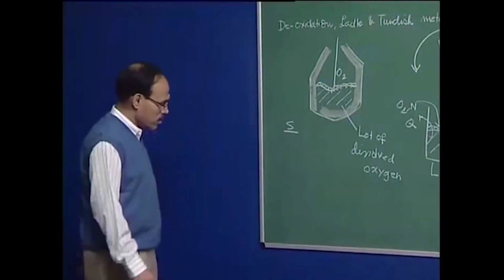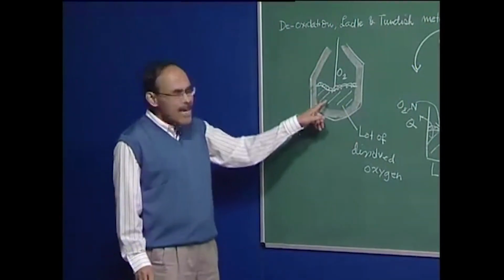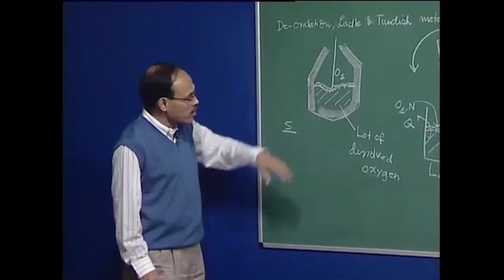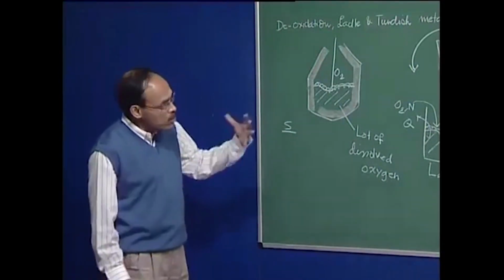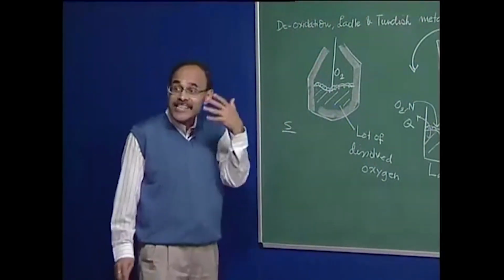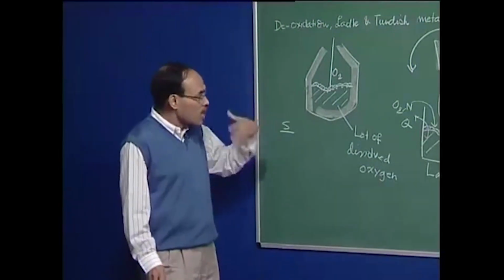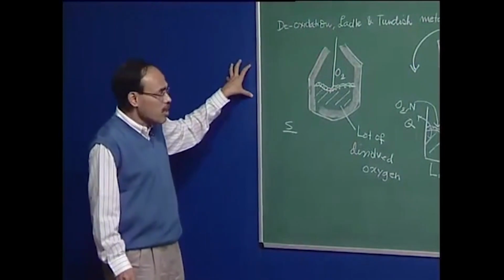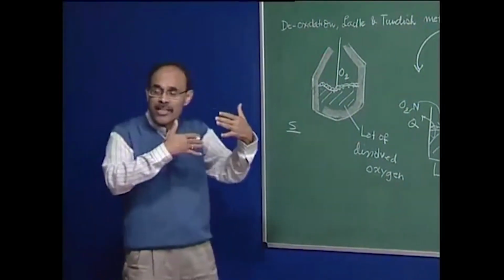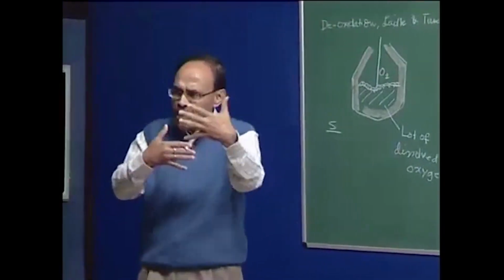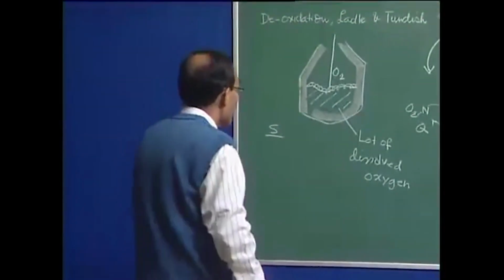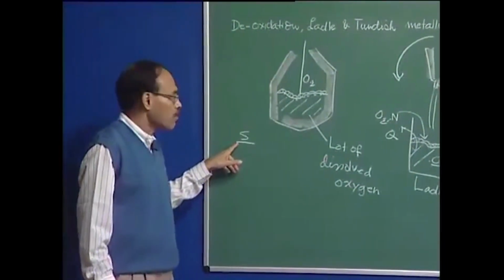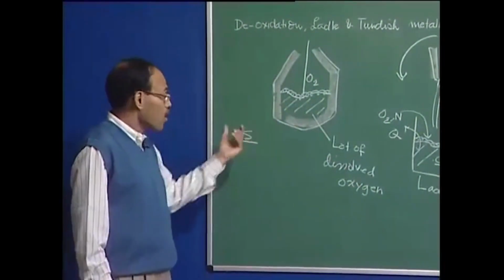which is more than the required specification, although we would like to have phosphorus absolutely at the right level. I must also mention here that there is an increasing trend that for high phosphorus steel we are going to have some kind of pre-treatment, which you of course have done. That between blast furnace and primary steel making, we have pre-treatments like desiliconization, desulfurization, and we are gradually building up dephosphorization as well. So we can have a lot of sulfur in the basic oxygen furnace, and we know why sulfur